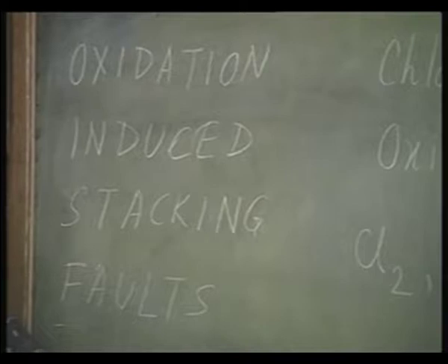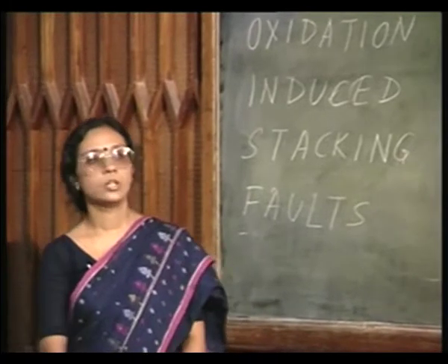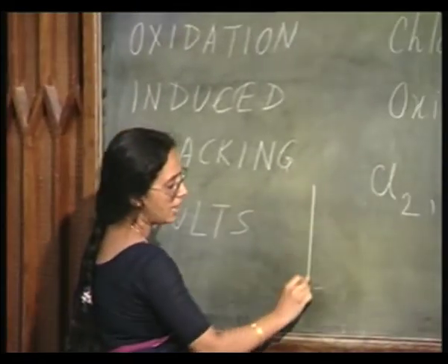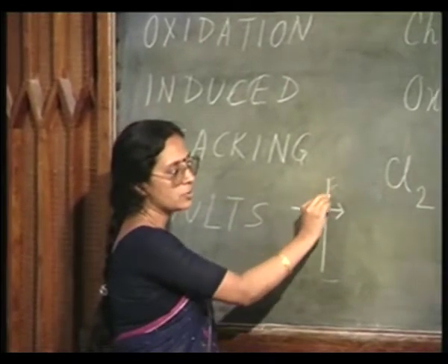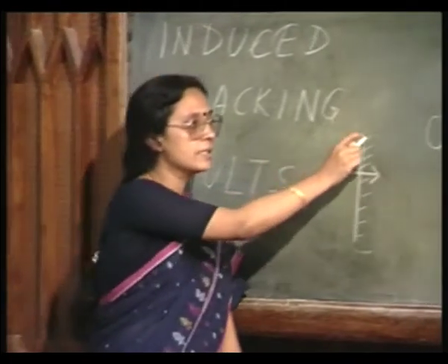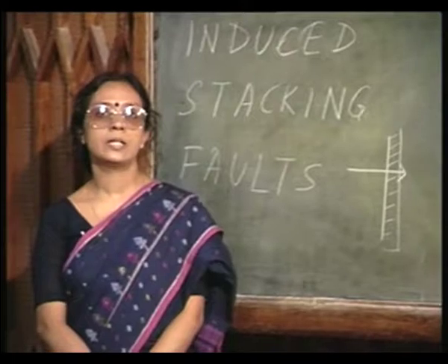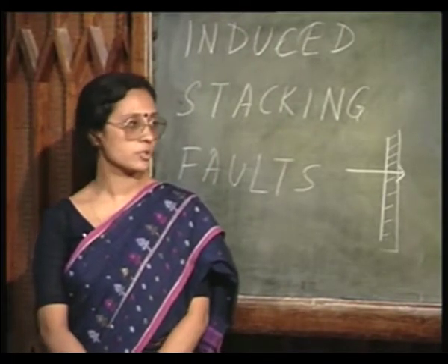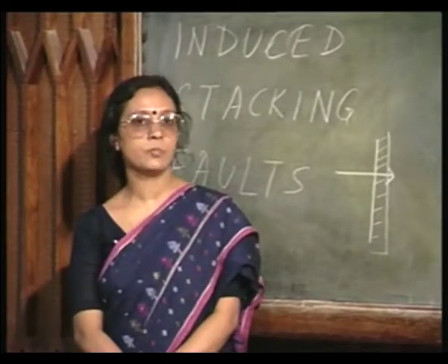At the time of thermal oxidation of silicon, the oxidation is taking place at the interface at the last, because the oxidizing species are moving inside. As the oxidation process goes on, the oxidizing species move inside, and this is where the oxide is formed. Therefore, the oxidation reaction is taking place at the interface finally. Now, what is there at the interface? To begin with, it had a lot of silicon-silicon bonds, because it was part of the silicon crystal lattice with all the silicon-silicon tetrahedral bonds.